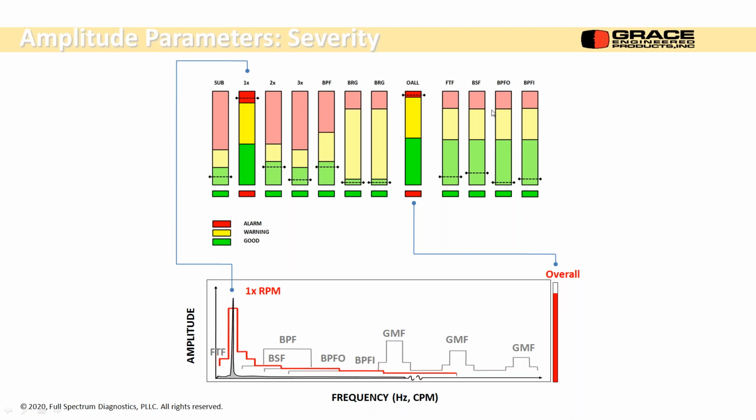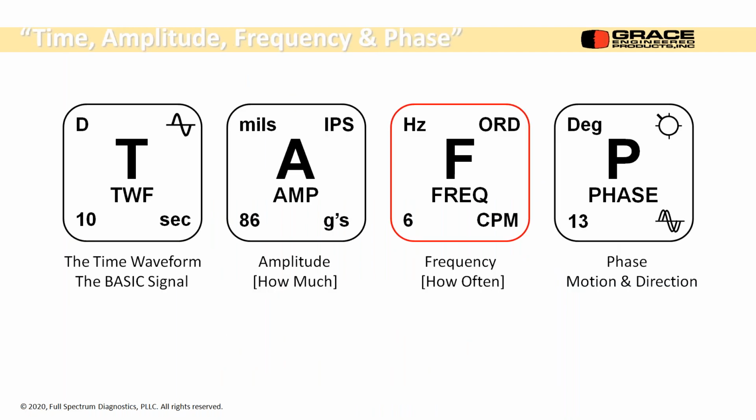If I know the bearings themselves, what make and model number it is, I can put a very narrow band in there and look for these frequencies to appear. And it's very subtle stuff in the background noise, and it'd be very interesting to pull those out statistically, which shouldn't be too bad. We're going to look at the frequency now, how often something happens.